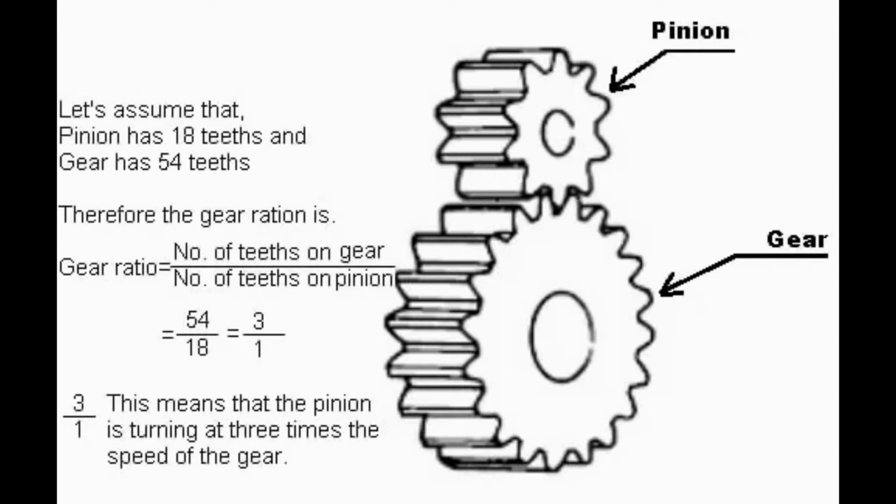Fuel economy is the main factor, as when the load on the engine increases due to its self-weight or other load conditions, the engine tries to combust more and more fuel in order to fulfill the need of the vehicle. Gear ratios are also needed to reverse the direction of the vehicle, which is not possible with a direct engine output shaft, and to transmit the power between two different shafts.